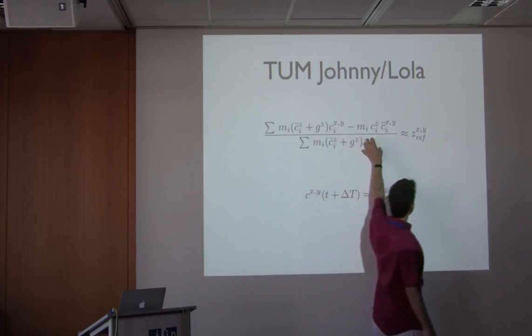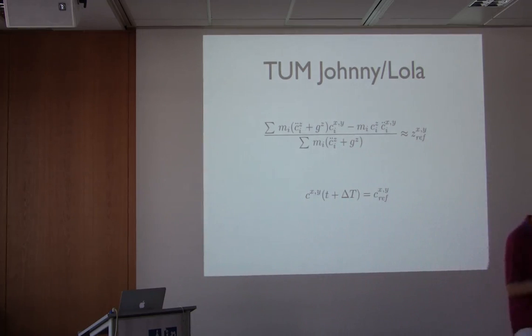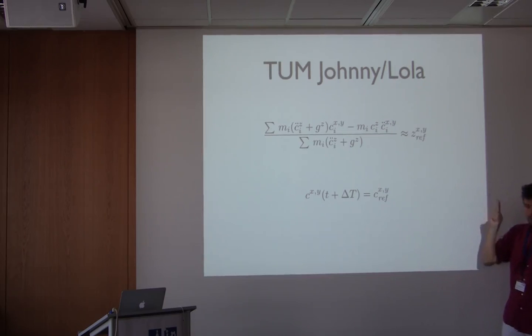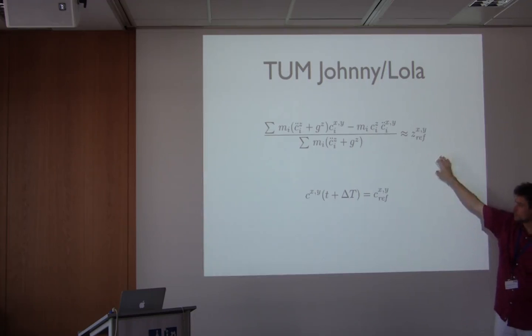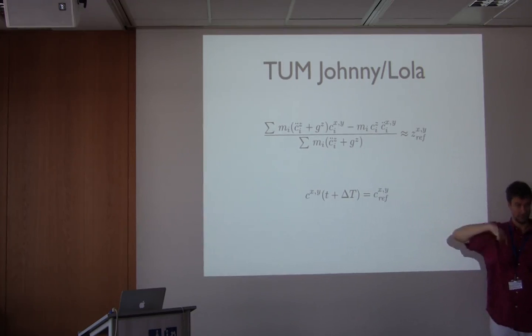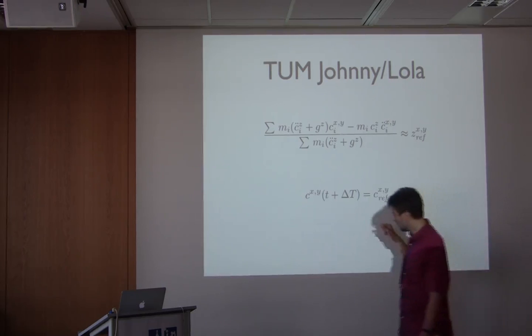Okay, and then they say, well, we fix the footsteps, we fix the motion of the center of pressure, but we leave 2 degrees of freedom free in this motion. So this motion is predefined except for 1 or 2 degrees of freedom. And these are used so as to impose that at the end of the motion, 2 steps later, the center of mass is there.